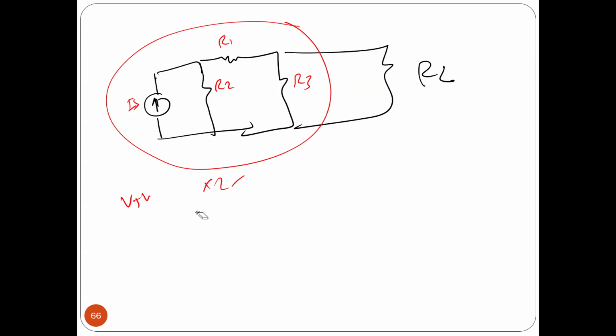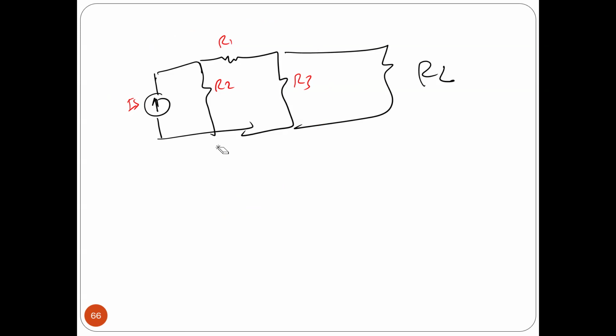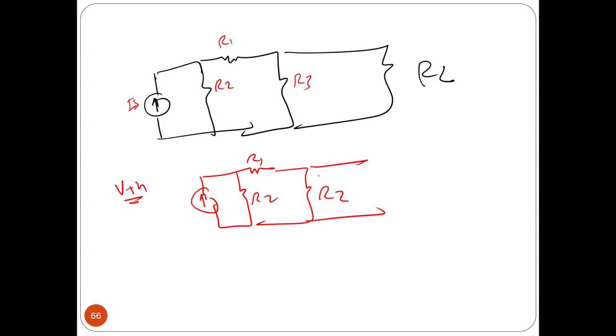So the way you have to do it, that's why you need, guys, for Thevenin and Norton, you need to draw the circuit. For example, because you are going to open it. If you're going to calculate V_th, I'm going to calculate it for this circuit. You need to draw the circuit here. I just want to understand what you are doing, not just picking some random numbers. You open the circuit and then you need to find the voltage here. At least start with this one, and then you show me how you did it.